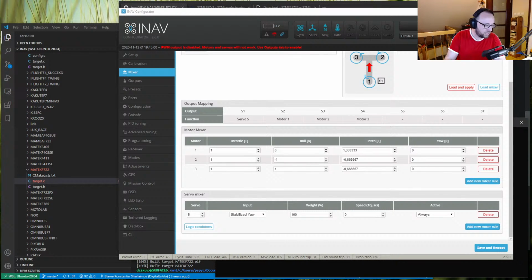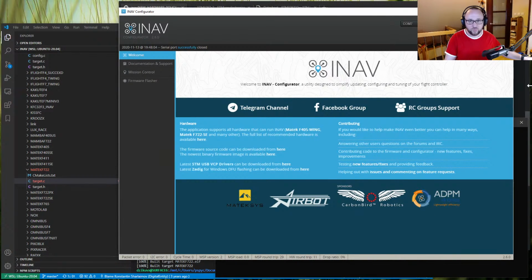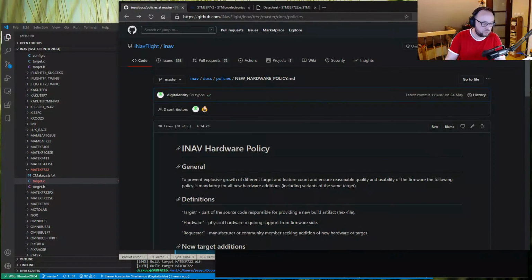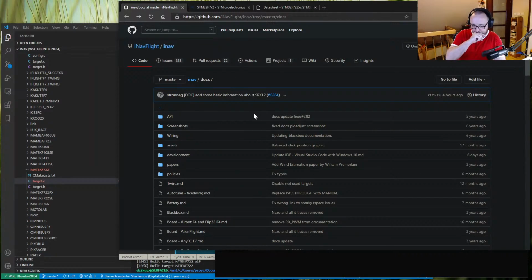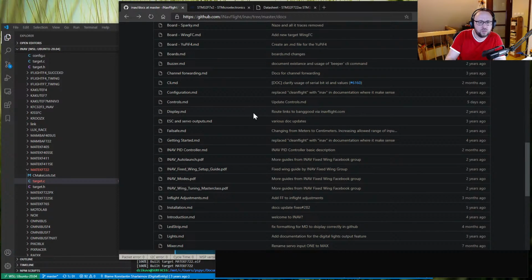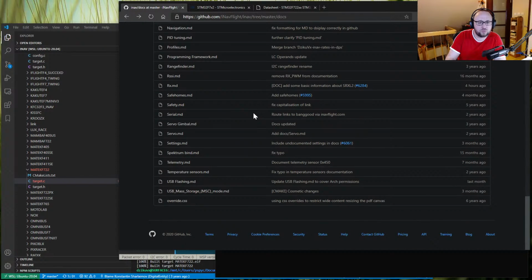Brian Ladmiraut also has a question. Can somebody use extra PWM outputs to control external devices using relays? Yeah, kind of, yes. Please do remember that you cannot drive a relay directly from any outputs on the flight controller, because you will just fry the flight controller and that's all. However, there is something in INAV that's not officially enabled anywhere, which is called Blinken lights. I do not remember the exact name, so